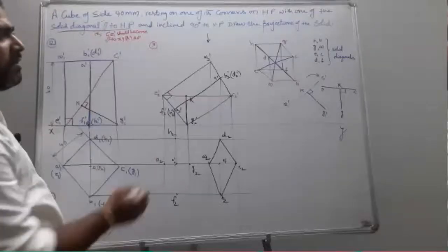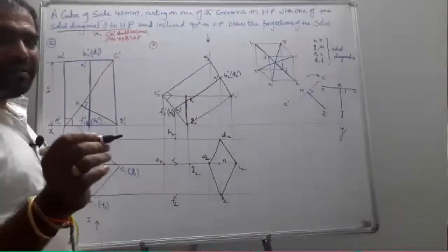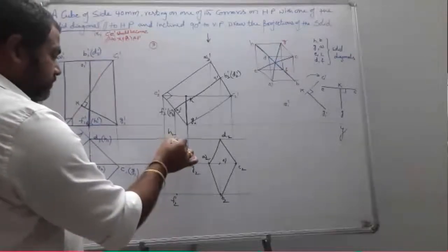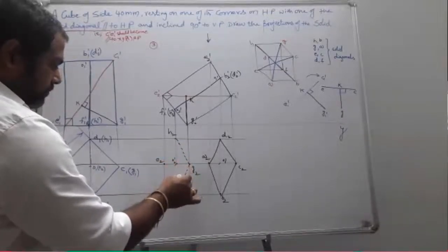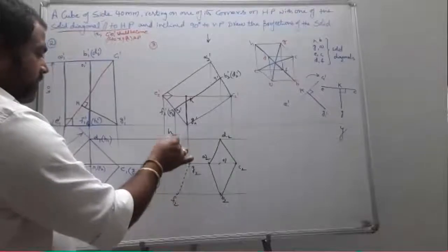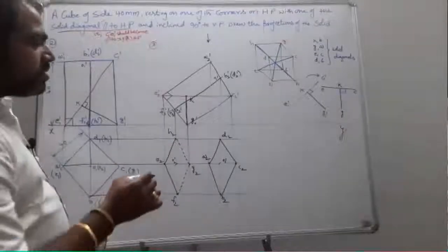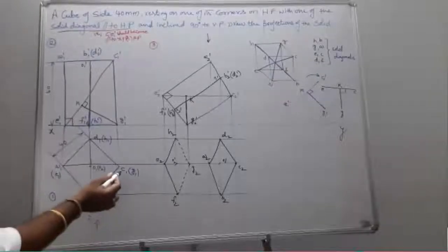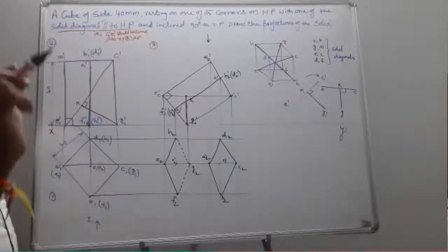Now our principle is, when I am supposed to see from this point of observer, let us take the farthest point from the observer, which is G. Lines which are passing from G are going to be the dotted lines or imaginary lines. And the remaining I just draw as solid lines. Now, once I acquire the two bases, I am supposed to join all the corresponding corners. That is AE, BF, CG, DH. These are the corresponding corners joined with the straight edges.